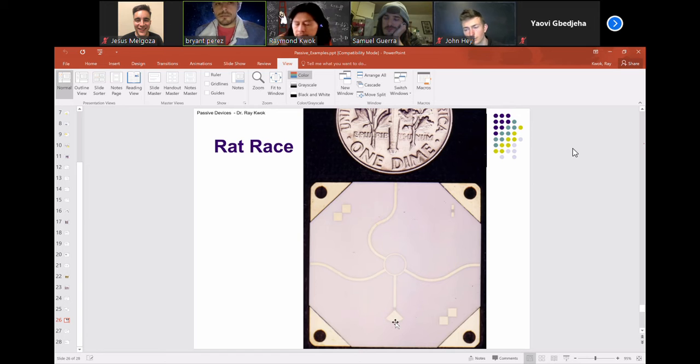I see. Thanks. What's the purpose of all of the other stuff that's not in the main circuit? This is to test the resistor, the etching, right? Sometimes they etch too long and expose more resistance. So this is supposed to be 50 ohms, and I'm going to test it with an ohm meter. Instead of testing the real circuit, I want to have a test circuit on the side. So if it's not 50 ohms, that means something's wrong with the etching, right? The other squares are mostly for visual. If they etch too much, then you don't have the corners connected together or something like that.